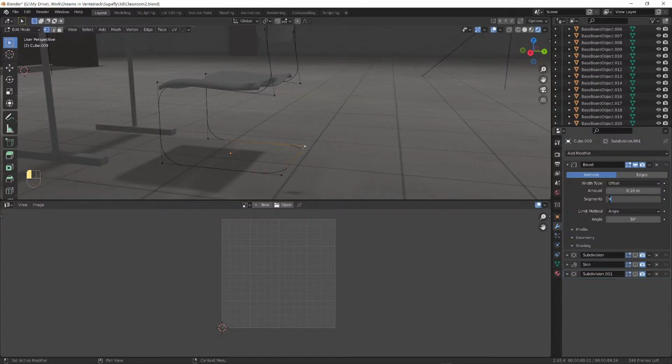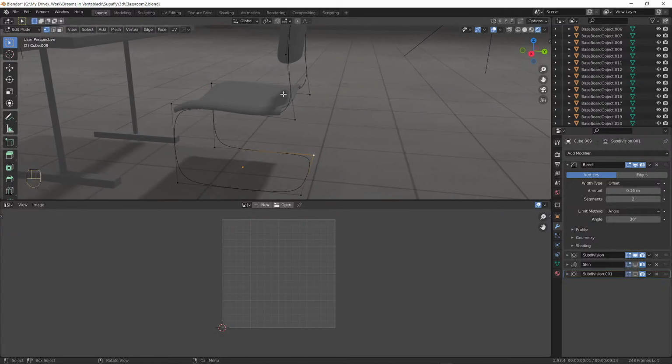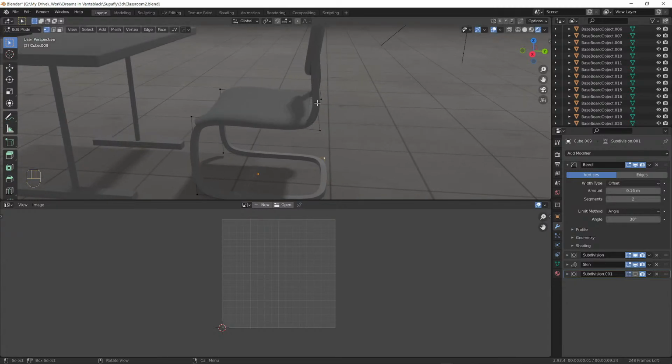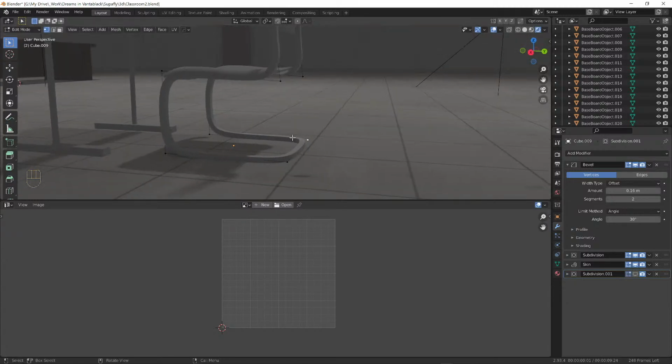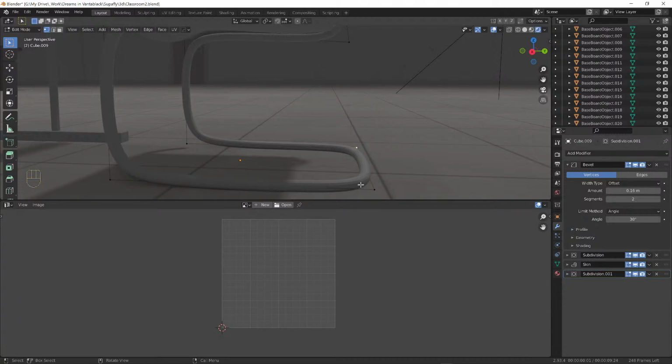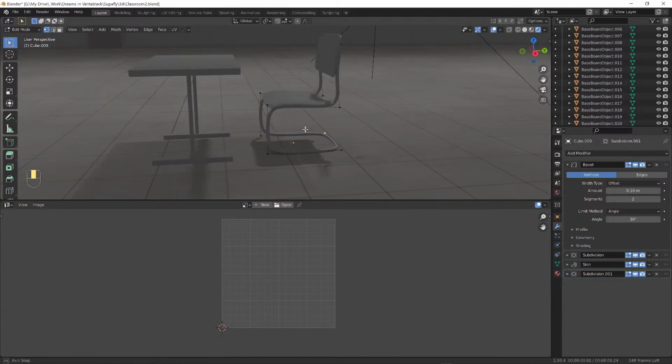And then I turned on a subdivision, but I didn't rely on that. Set that to 2, and then I use a subdivision surface modifier, which takes what I have there and starts smoothing it all out. Then I had a skin modifier. Skin modifier basically takes a wire or just an edge and adds a thickness to it. So that's what's happening there. And then I subdivided that one more time to get the roundness going around it.